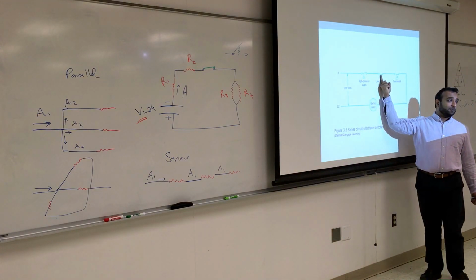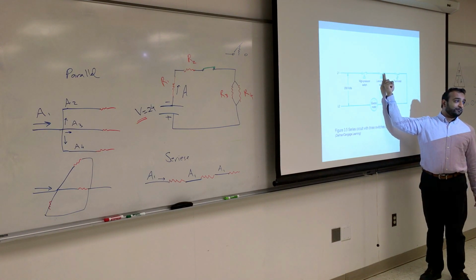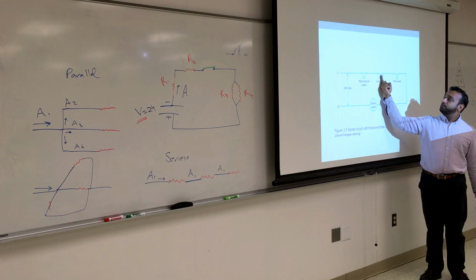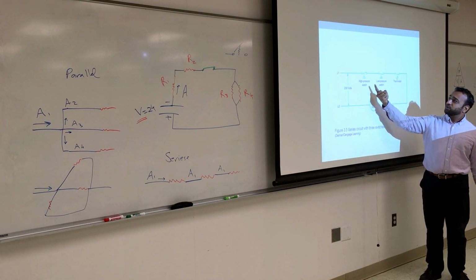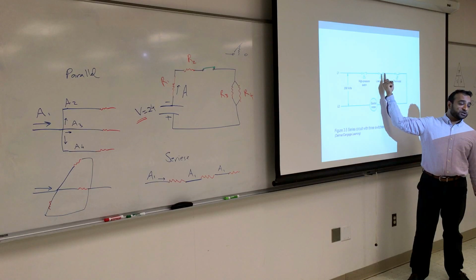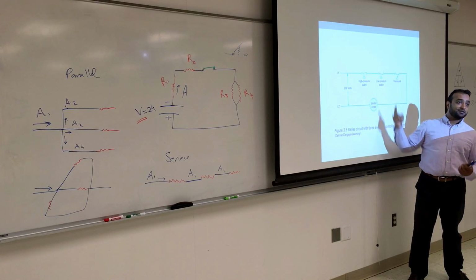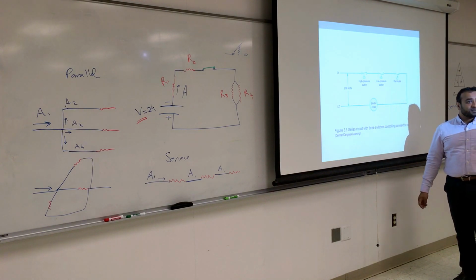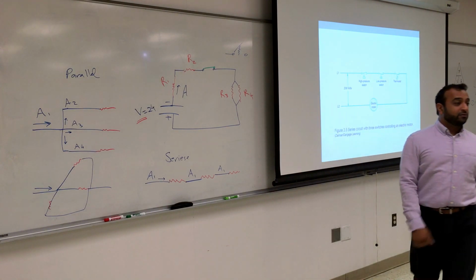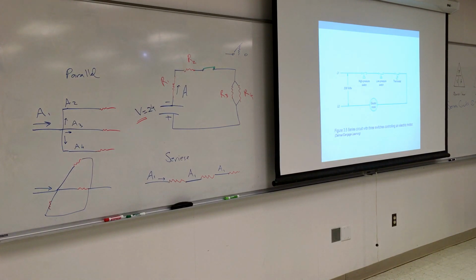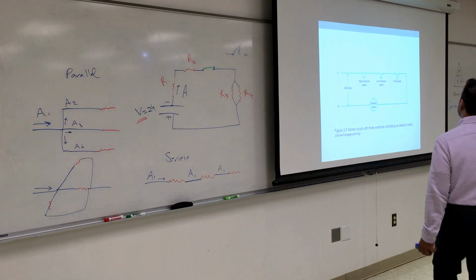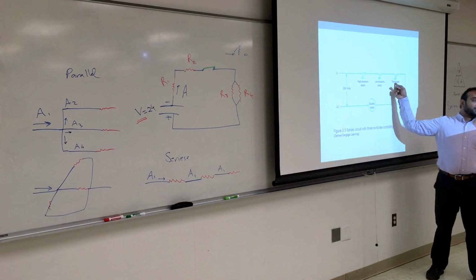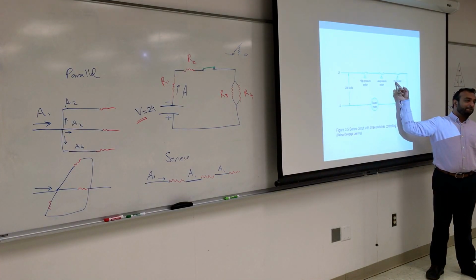The pressure is too low, it will again pull up and close the circuit. So this will disengage and this will engage when we have low pressure. The opposite action. And we can set the limits for both of them. And this is a thermostat. This thermostat again usually comes from the room. So if the room is cold, there's a call for heat. The thermostat will engage. So this is called a heating thermostat.